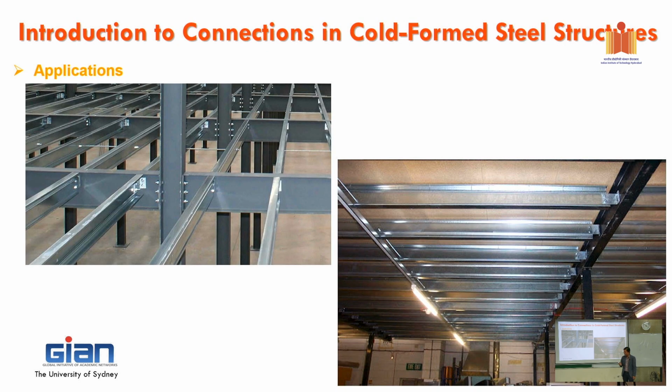So there's a lot of things for cold form steel. And I think bolting is probably too strong for cold form steel. Bolted is for hot roll steel, but for cold form, yes, in some applications like this one with a bigger section, but for a smaller section, screw is more practical.